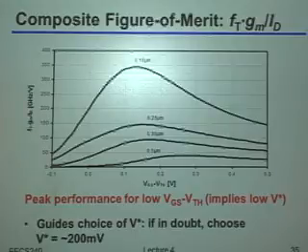In other words, how do you get both a reasonable speed out of the device and a reasonable current efficiency? Okay, so that's where this so-called FT times GM over ID metric would come from. And it's just saying, if I had an ideal device, I would want this metric to essentially be infinite, right? And if I don't, then I can look at what are the regions where this composite metric gives me something that looks reasonably good in terms of balancing those two things out.